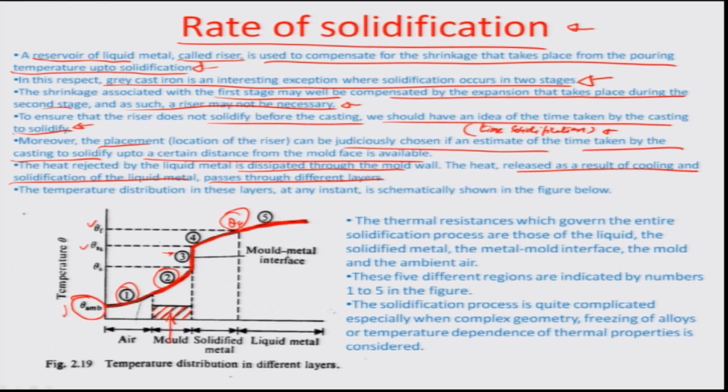So, the resistance to the temperature here is offered by the metal, here it is offered by the solid metal. Here again it is basically a function of the way that the solid is coupling with respect to the mold wall. There may be a small film, for example, formed, and we will do all these cases independently when we do problem examples. There may be another case here where the mold itself provides thermal inertia, thermal resistance, I am sorry, and then it again takes down the temperature, and then obviously the ambience around the mold wall is also responsible for the same.